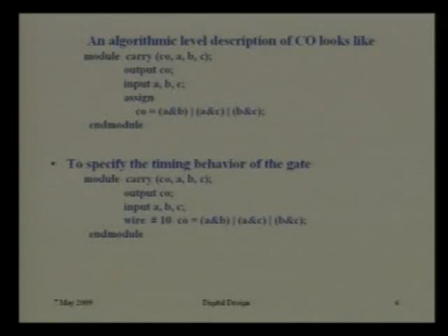It is the same thing, only I have given hash 10 then CO equal to. What does this hash mean? You will be learning that very soon; it is actually the delay. At 10 time units, whenever we write some unit we will define it, picosecond or nanosecond, with some hash define. So after 10 units only is your carry output available.